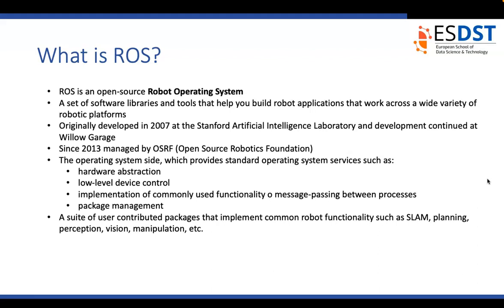For example, you have a process used for the motion of the robot, and another process used for camera configuration and detection. You need to tell the robot that when the camera detects something it needs to move, so these processes need to be talking to each other. ROS is very helpful here. We will see how it helps to send information between these two.